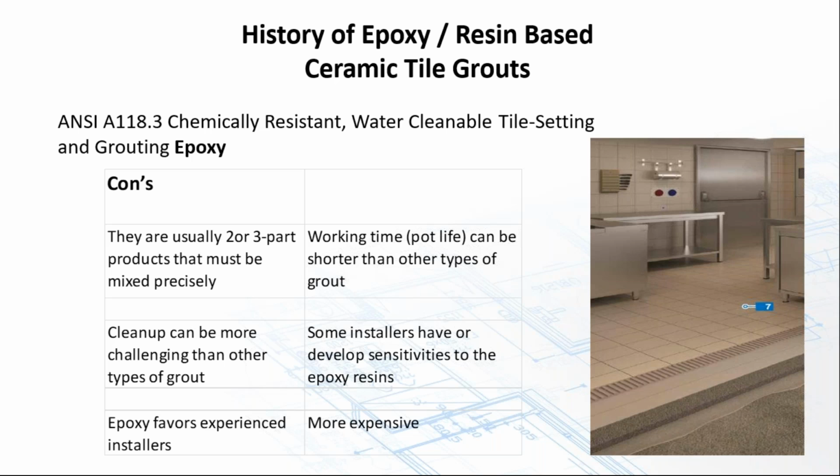If you're not using all of the parts to their fullest, you may end up with a failed grout. The grout might not harden properly or become soft, because all of the chemical, all of the product is needed to get the proper set with it. It's like baking a cake. If you don't put in all of the ingredients, it's not going to turn out. Similarly with these epoxy grouts, all of the ingredients from the different components going into mixing up the unit must be used.